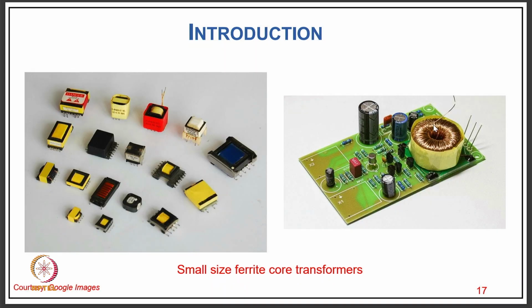There are also many transformers for high frequency applications, typically used in power electronics and electronics transformers, which are normally made with a ferrite core, not laminated steel, because the power is also low. Apart from that, when we go for high frequency, the size of the transformer is reduced for the same amount of power.